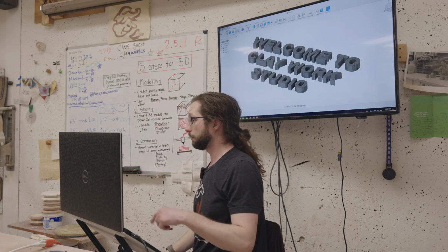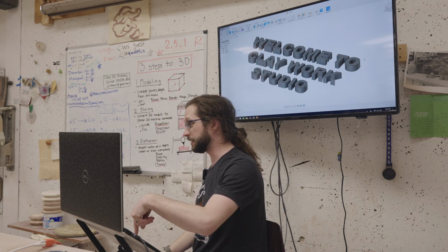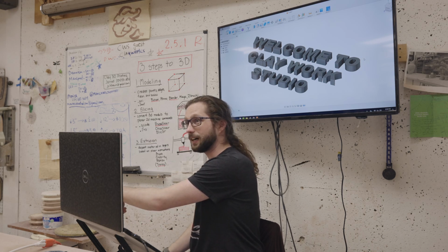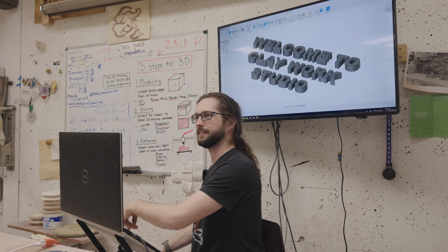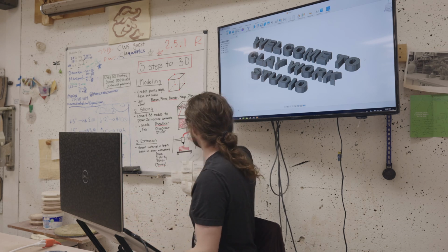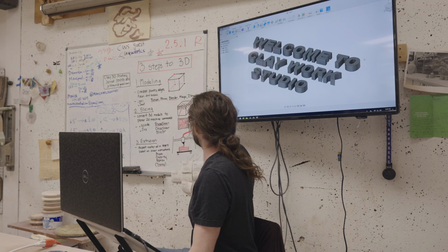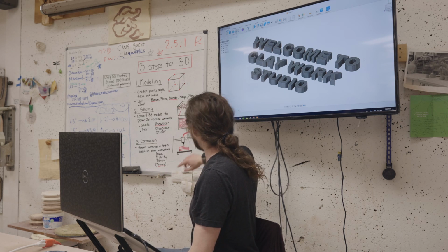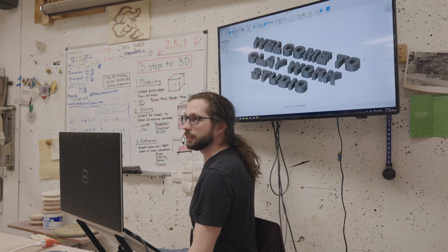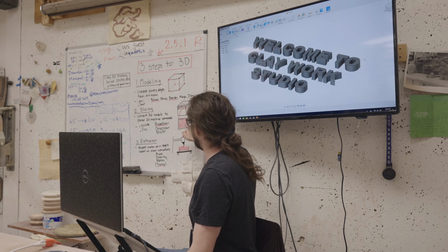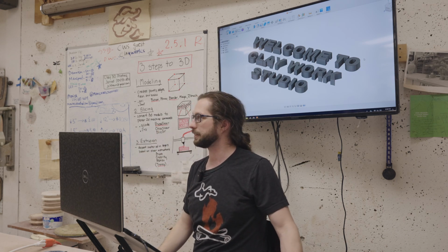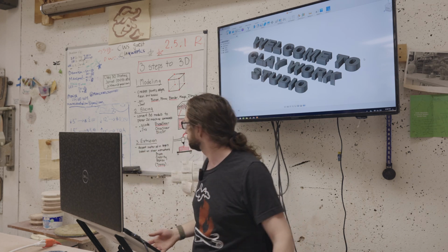It'll be like move from x90, y30 to x100, y50. Or extrude at the rate of 10 millimeters cubed. It's a bunch of commands that the slicer is telling the printer how to print. And so that's the output of the second step, a file that we can actually put into the machine itself that has the steps to follow.